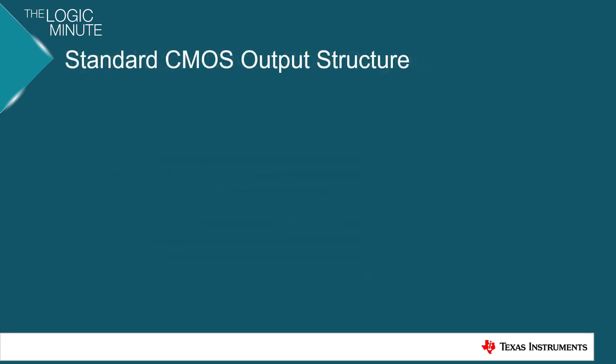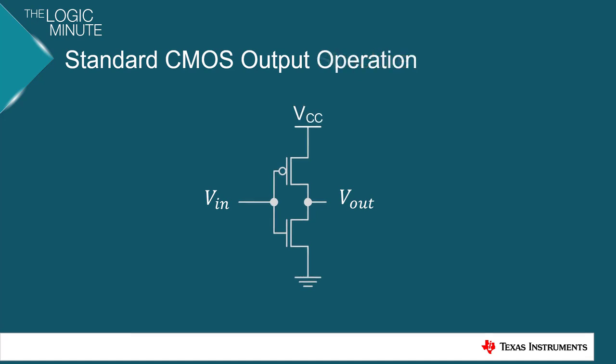There are many variations of circuits used as outputs for CMOS devices. However, the most common is the very simple CMOS inverter. Vin indicates the control voltage coming from the internal logic function, and Vout indicates the output voltage of the device. The MOSFETs in the output structure are voltage controlled, and their control voltages are defined as VSG and VGS.